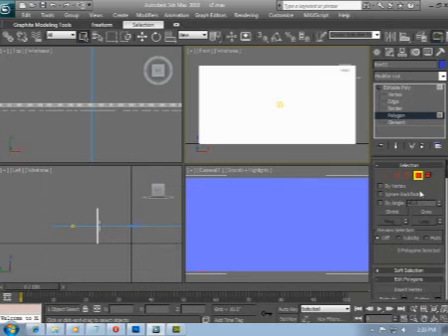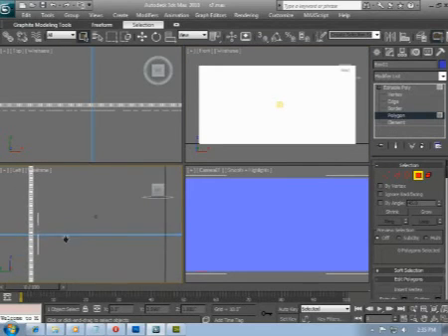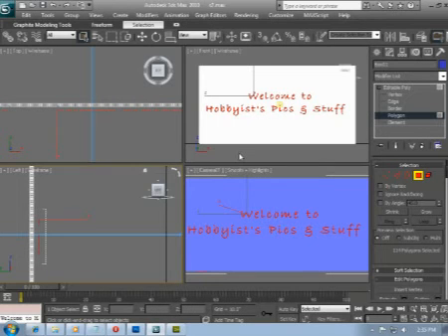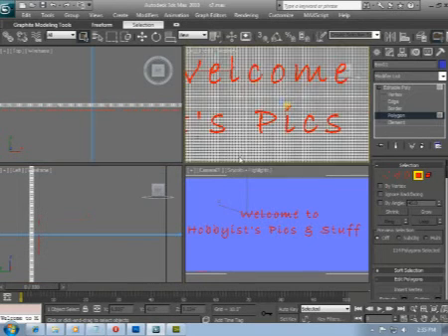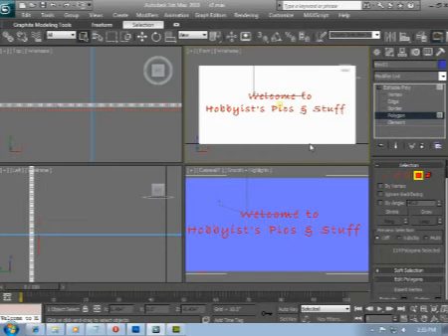That lets us know a lot of things aren't going to work right until we get back out of sub-selection mode again. Let's click the Selection button and make sure we're making a square shape selection. Then let's right-click in the left view and select the polygons that used to be the text object. And if we right-click and then wheel in front view, we see the text polygons selected and ready for pulling out our text pattern.